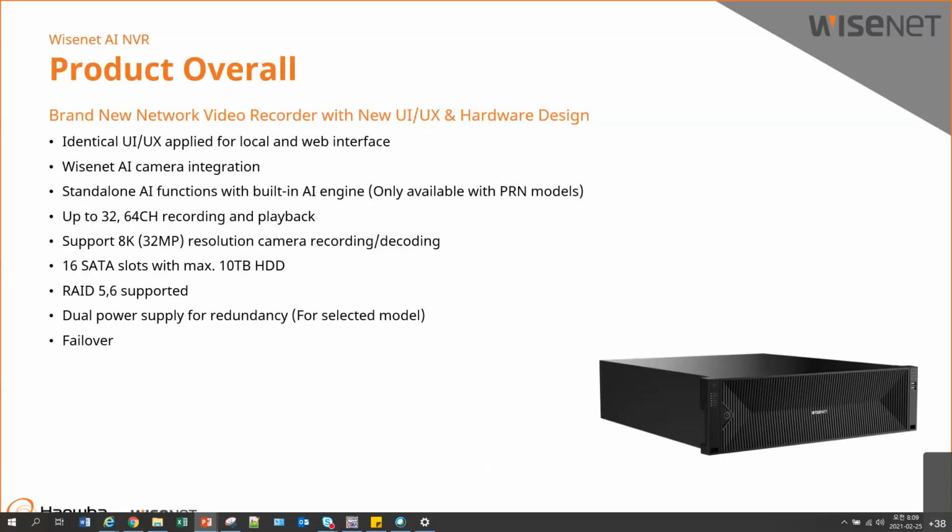Also, Wisenet AI cameras will be integrated. And for the AI NVR, standalone AI functions with a built-in AI engine will be available. It supports up to 8K resolution, which is 32 megapixel camera recording and decoding. It will have 16 hard drive slots and support a maximum 10 terabyte hard disk. Of course, it will support RAID 5 and 6, and some products will support dual power supply for redundancy. And failover will be supported for every NVR.